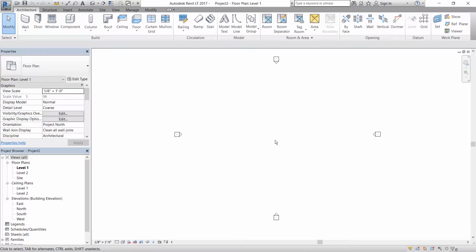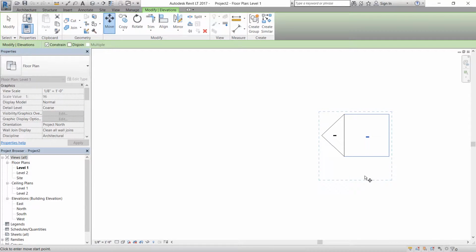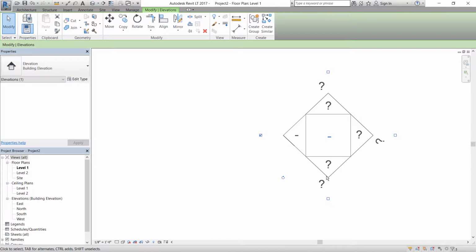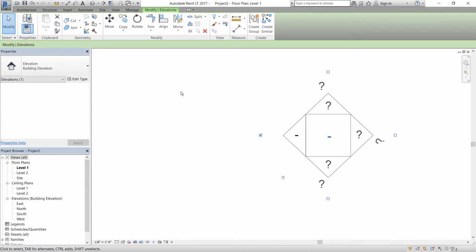I'm going to go through all the basic selection methods, but before I do that, I just want to go over how object selection and command tools work with each other. Revit allows you to select an object and then activate a modify command. Whenever you select an object first, Revit will open the contextual tab Modify. From here, you can go on to selecting a tool from the ribbon or use a shortcut.